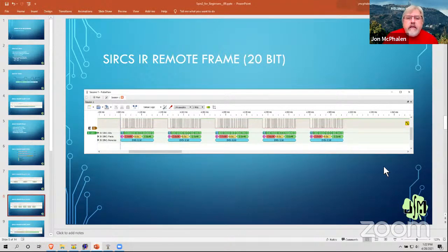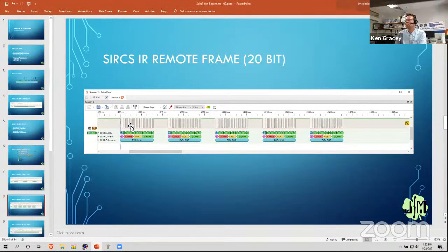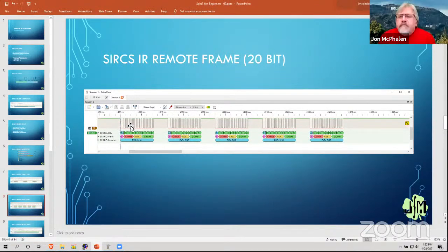So again, getting back, this is our 5 packet. If you round up and call a packet 50 milliseconds, you'll see a lot of times I will have, when I've received a code, I'm going to put a 250 millisecond delay before I allow myself to look for anything else. The reason for that is if I caught any of these, I just want to make sure enough time has elapsed that I've stopped sending repeat packets. So you'll see that in the code.